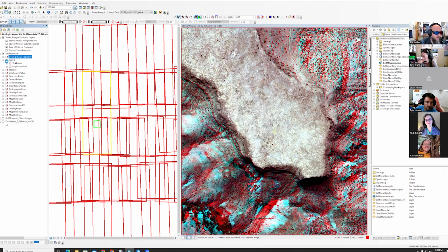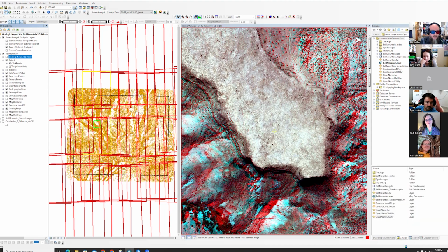It then compares all of the feature classes that are already in this layer file and ensures it finds the matching ones. And then with the matching ones, it'll go ahead and repair those broken links. Exactly the same as we had to do last time. Fundamentally, this layer file was connecting to a certain data set. We now need to connect it to the correct data set. In that, our create features templates has the same problem that it has in Arc Pro. We need to set our data sources. We need to set our location sources.